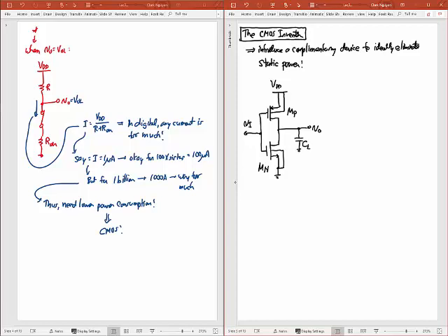So everything in an MOS circuit is based on capacitors. You're just charging capacitors. That's great because that means you're not losing any energy through a resistor to the other supply. And so let me just point out that we tied this and this the way they are to eliminate body effect.